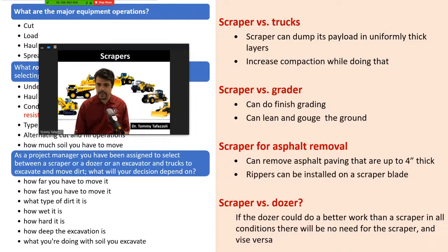Between a scraper and a truck, there was a good comparison: the truck cannot spread the soil, while the scraper can spread it in uniform levels. It accelerates the compaction process because you have your layers already and they are uniform, and the weight of the scraper could contribute to some compaction. Scraper and grader, we mentioned that both of them can do finish grading, so they're both good.